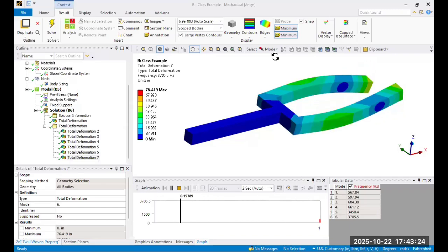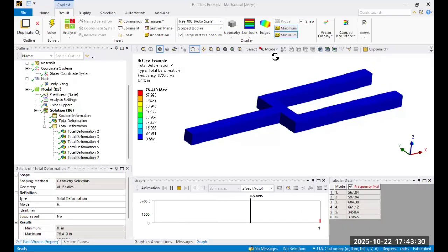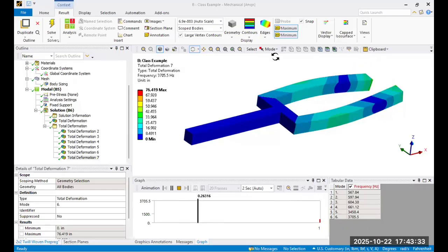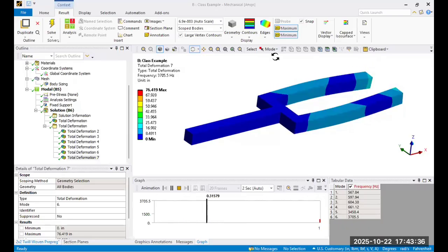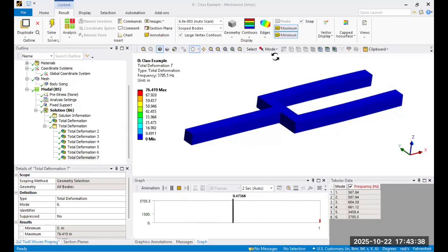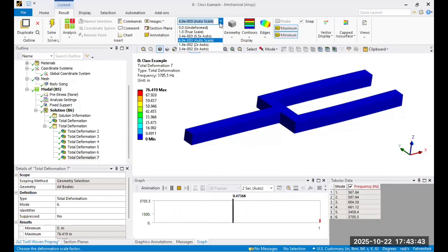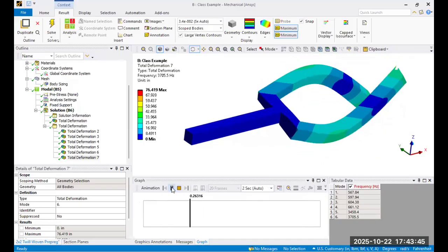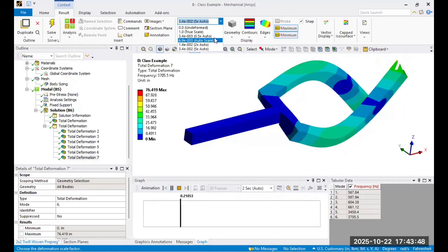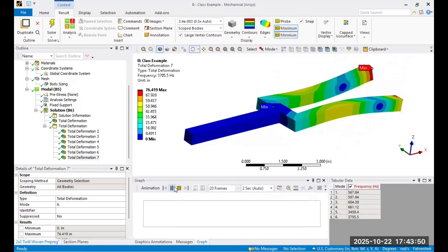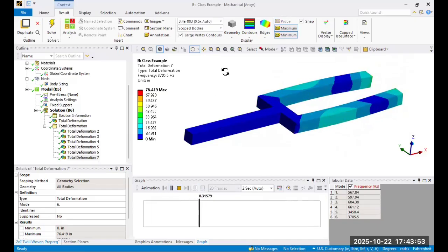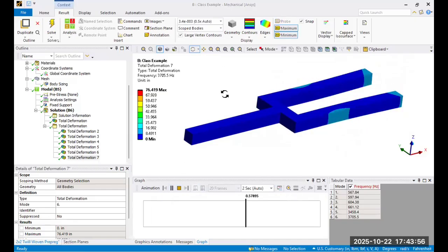And so you're going to impart a significant amount of dynamic environments into each of these blades. That's the second example. The third example is a launch vehicle taking off. You're going to have significant engine vibrations that go up and down the vehicle. You're going to have the aerodynamic environments acting on the vehicle. And these two loads combined will cause the mode shapes of the vehicle to be excited. So what happens there, we need to consider that dynamic amplification that occurs due to these input environments.